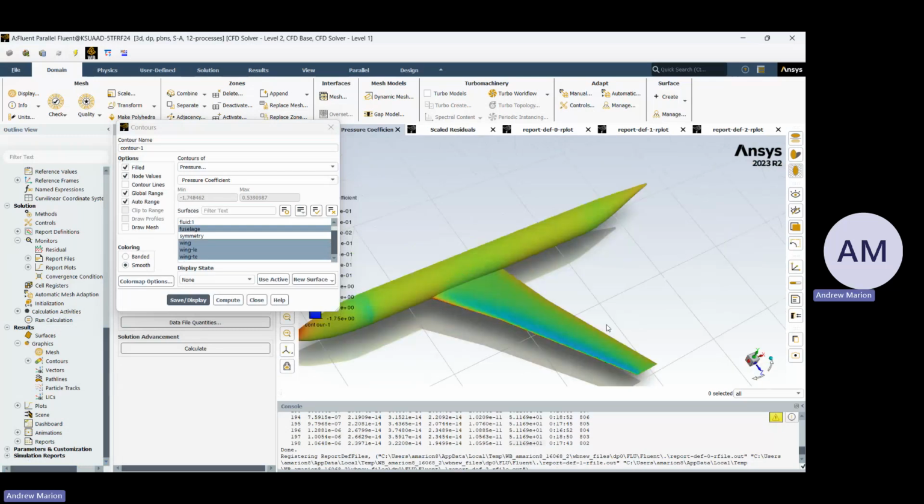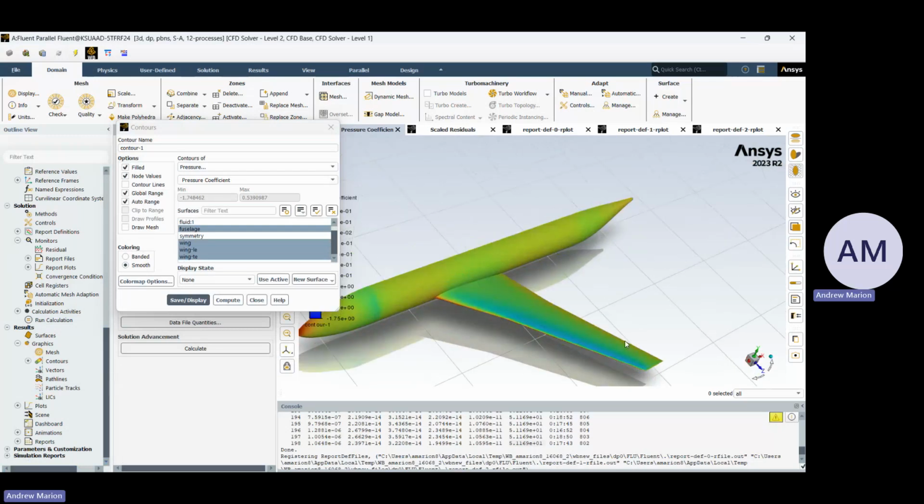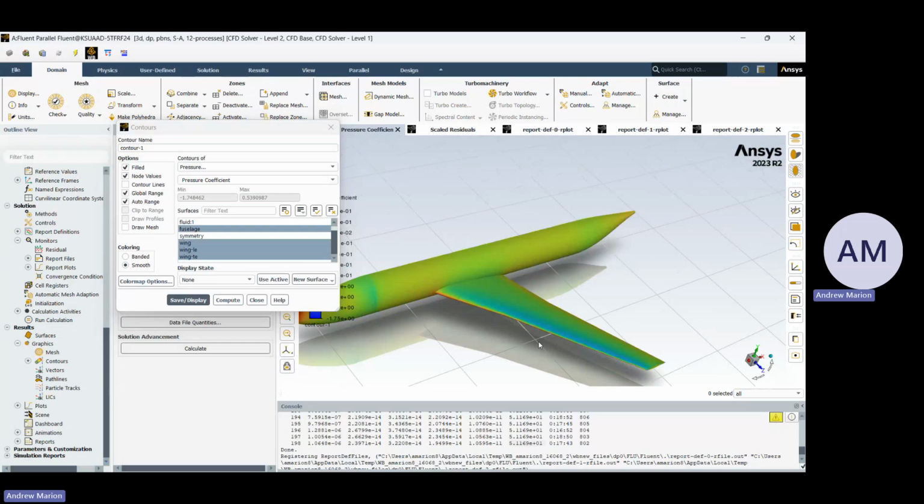And you also see further down the line, because there'll be leakage at the end of the wing, this high pressure air at the bottom is circulating around the wing and trying to get up to the top. And that creates the wingtip vortices you see. If you've ever seen an F-22 flying, you can see those vortices sometimes if it's cloudy out. And so if this is your wing and the air is coming at it like this, the air on the bottom is going to be high pressure, and air at the top is going to be low pressure.